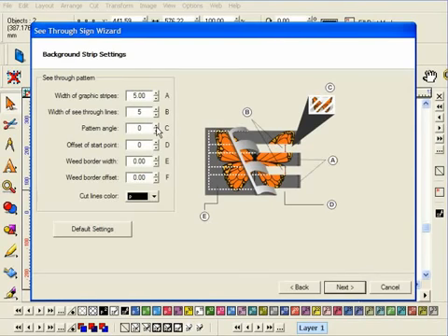The lines on this design are going to run horizontally to the image, however this angle can be changed by entering a value here. The stripe lines that are applied to the image will start from the baseline and work up, however it's possible to specify an offset so that they are brought in from this edge. To do this, simply enter an offset value here. The value is set as a percentage of the line width that's been previously specified.